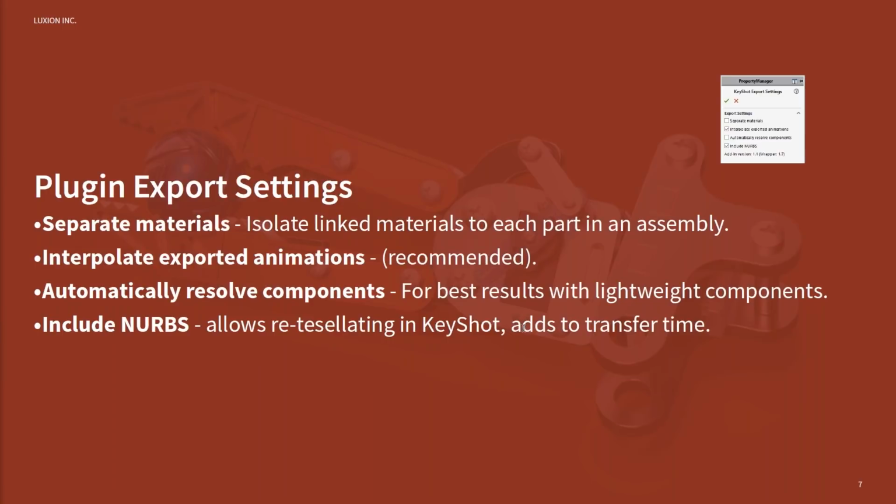And actually for now, it is not remembered when you close and reopen SOLIDWORKS. So just make sure to check those settings each time you're opening up a new session of SOLIDWORKS, just to make sure that you have those enabled correctly. So yeah, if you do find that the transfer time is taking a long time, check to see if NURBS are included, and you may want to disable those.